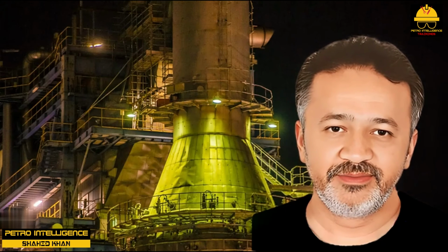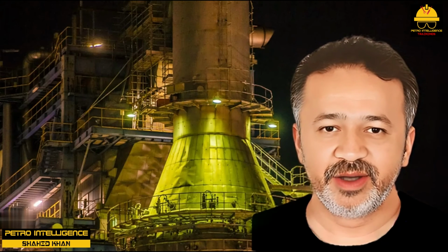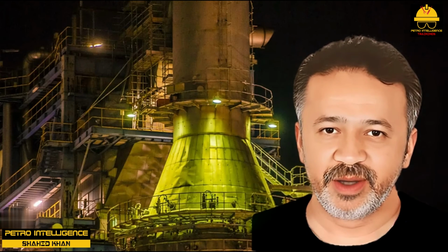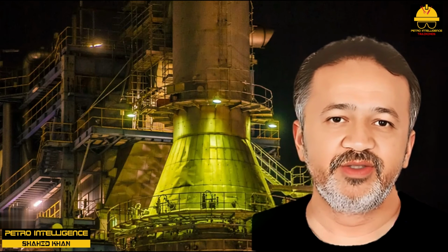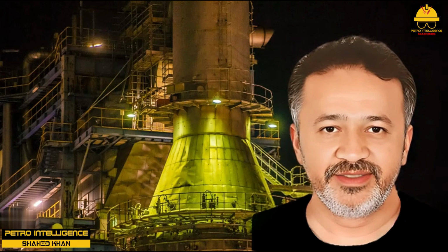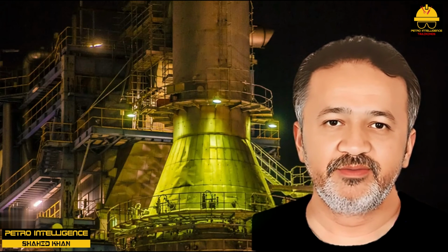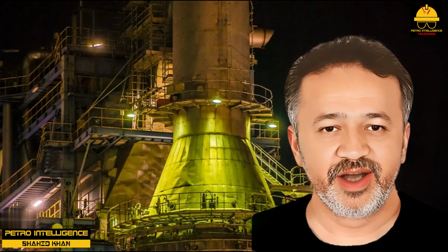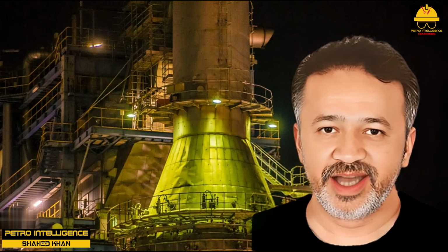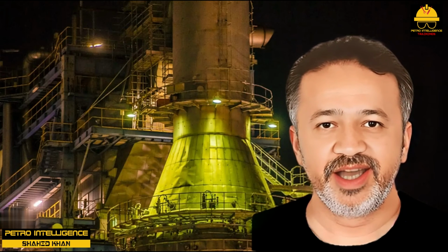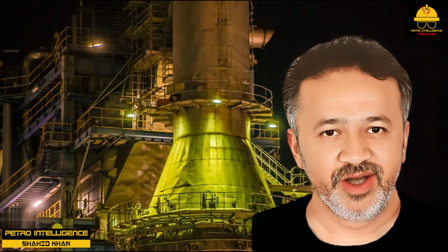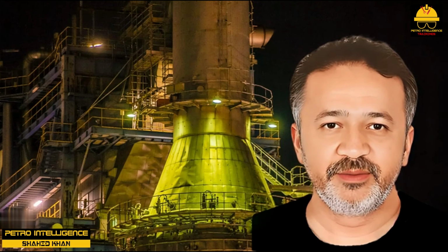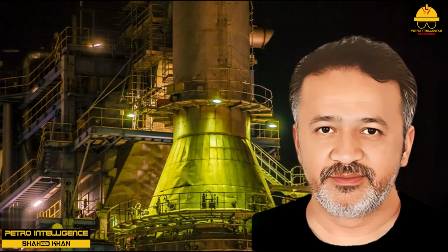Preheater vibration. Air preheaters or any type of waste heat recovery device designed for horizontal flow across vertical tubes may be subject to vibration produced by the velocity of gas across the tube banks. The velocity produces a vortex shedding wave pattern that could correspond to the natural harmonic frequency of the tube bank. If the natural harmonic frequency is reached, excessive vibration of the tubes will occur. Redesign of the internal baffle system by inserting dummy baffles can stop the vibration.